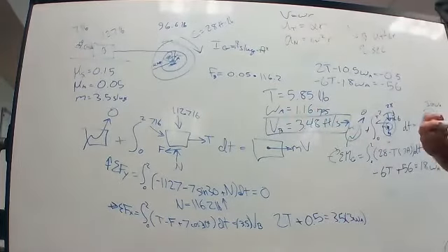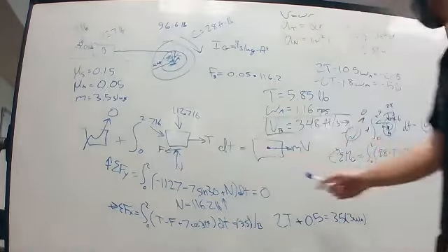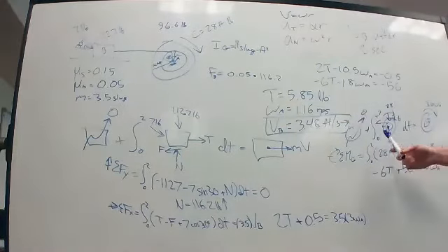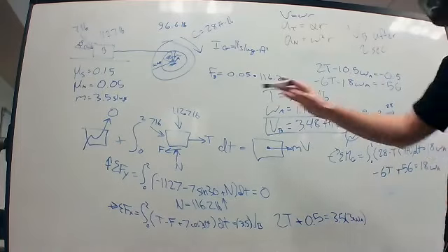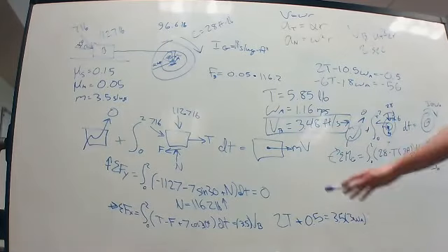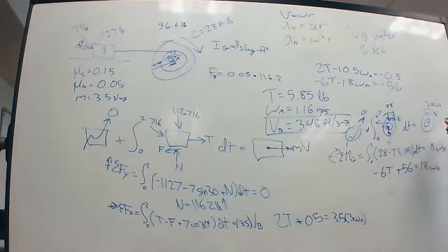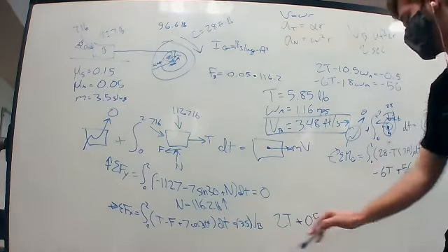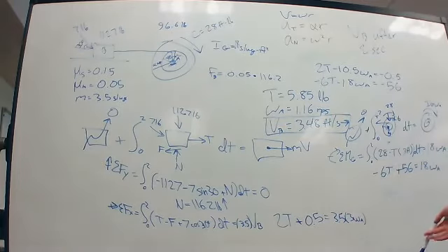So the idea here is that we set up the block diagram and the wheel diagram from integrals from 0 to 2, because that's our time constraint, with all the applied forces and then the expected motion with translation to the right and the rotation clockwise. You can solve for them and replace anything you know, like we established that V is equal to omega R, because otherwise we would have VB and omega, and then we have 2 equations and 3 unknowns, and we can't get anywhere.